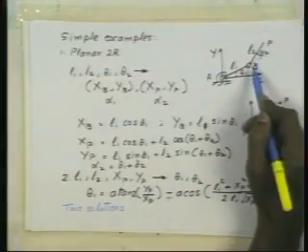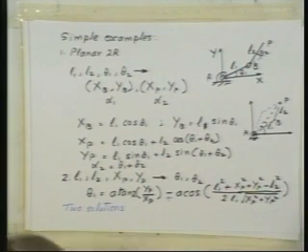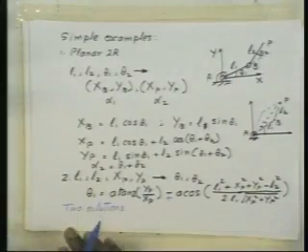Right, the actuator is mounted on the link, and if you think about the control problem, it is the motors that we have to rotate in order to make the joints rotate, right? And the angle the joint rotates by is essentially the angle by which one link rotates with respect to the other. That is why the joint variable is defined here as an angle made by one link with respect to the other rather than with respect to the base link. So the angle between the two links which are at the joint. Okay, so these are things which we will do in a more systematic way when we go to specifying this for spatial mechanisms. This is a fairly simple planar mechanism case.